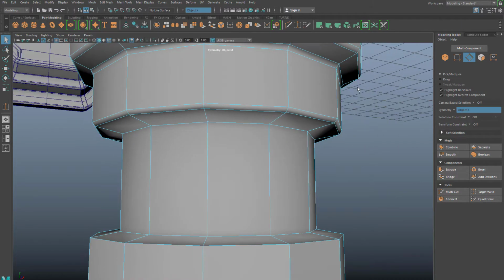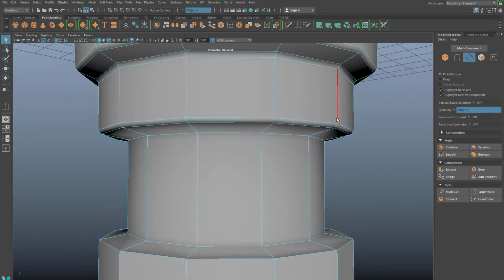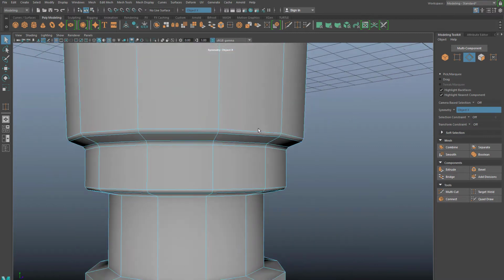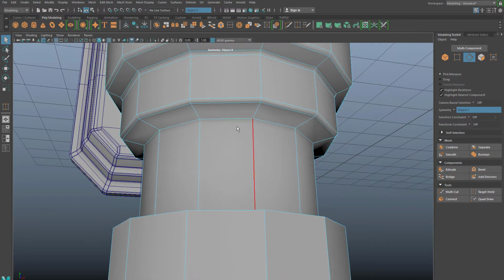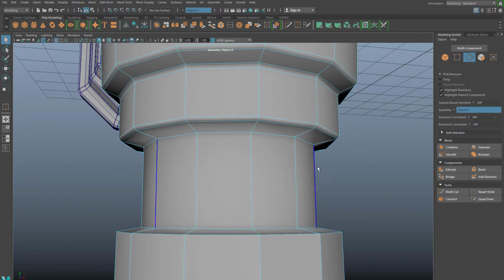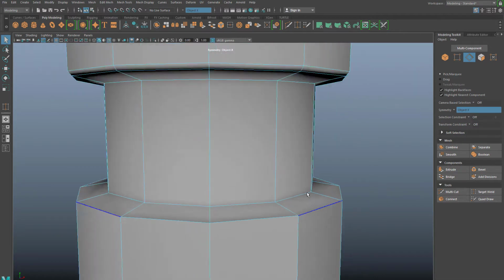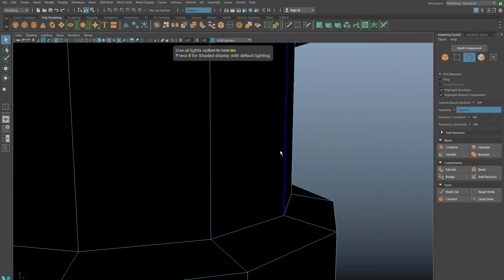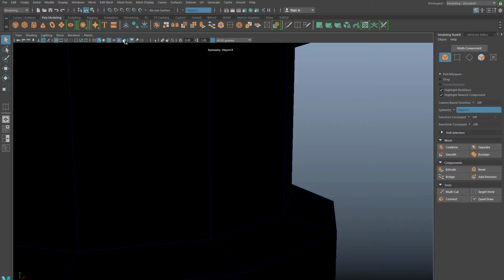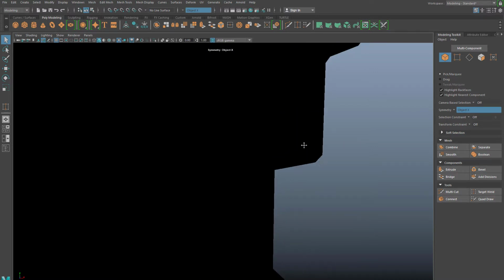But the normal map is really going to be what's going to create that transition. So you don't have to worry that much about leaving these edges or not. Generally speaking, an outside is going to be more valuable than the inside, because if I look at the silhouette of the object here, you're really not going to be able to see that transition right on the inside, whereas on the outside you'll be able to see more of that transition.